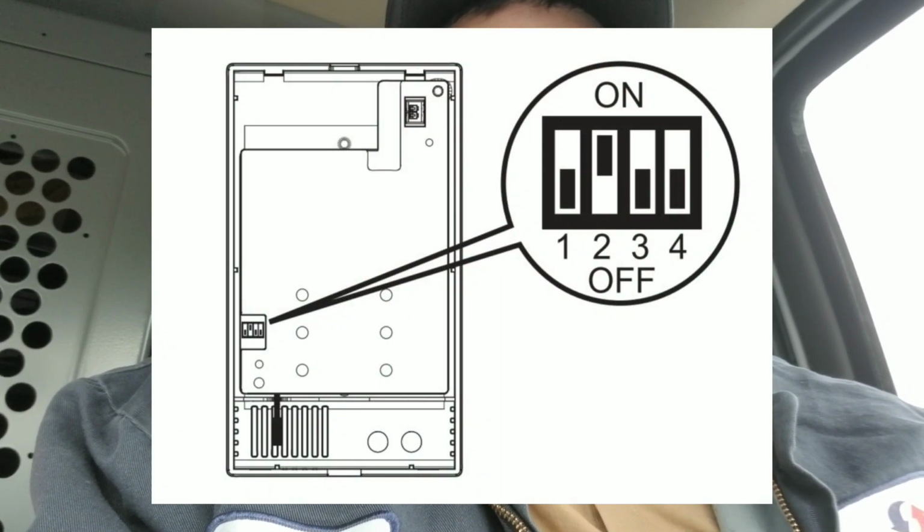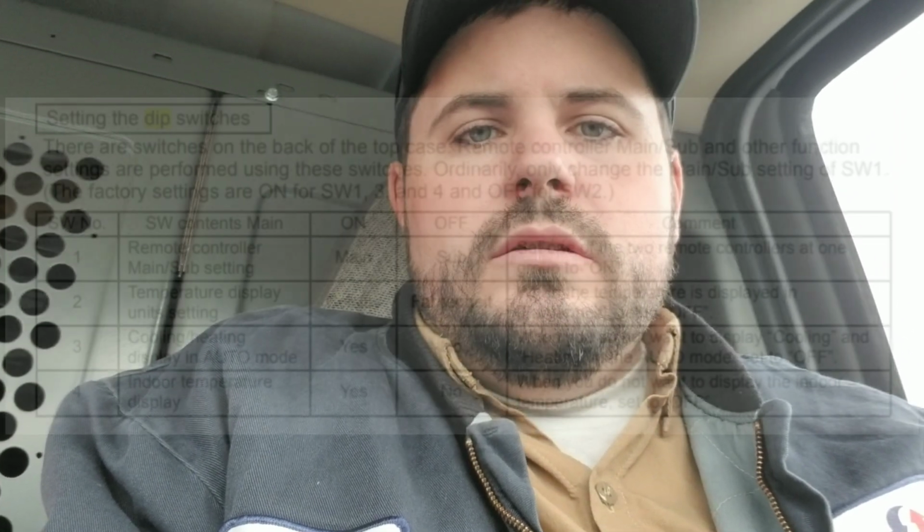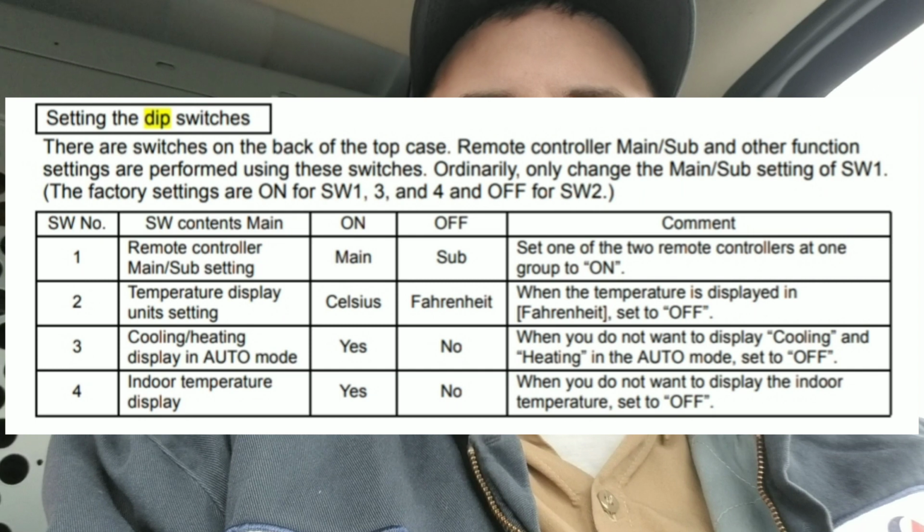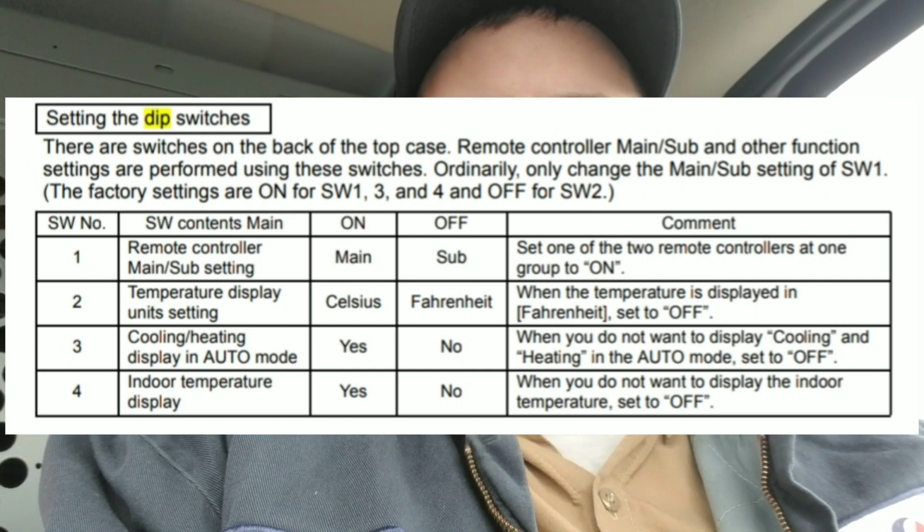And so you have a punch list of things to check, and we had good connections, wire wasn't nicked, there were no continuity problems, it wasn't run next to any high voltage. Everything looked good on the wiring side. And so before I started replacing stats or boards, I wanted to check a couple other things. On these simple MA controllers, there's some dip switches on the back. One of them has to do with how it's controlling, whether it's working with other stats or not, and 3 of them are for display.